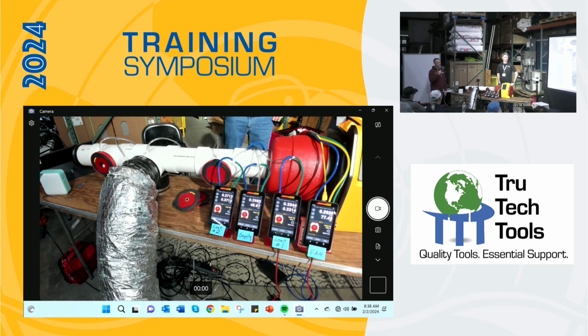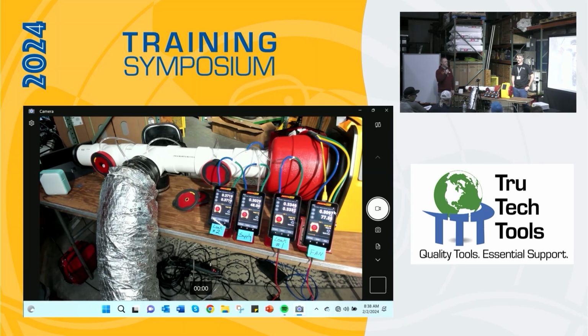So lots of diagnostics we could dive into on that, but fortunately we just don't have the time today to really do it, but we're happy to chat with you all about it later. But yeah, the point of this was just to show that it's all connected. You make one change, something else will happen down the line. So it's just good to keep that in mind, whether you're installing new ducts, repairing a duct, or sealing ductwork, it's going to have an impact on the pressure and flows of other parts of the system.